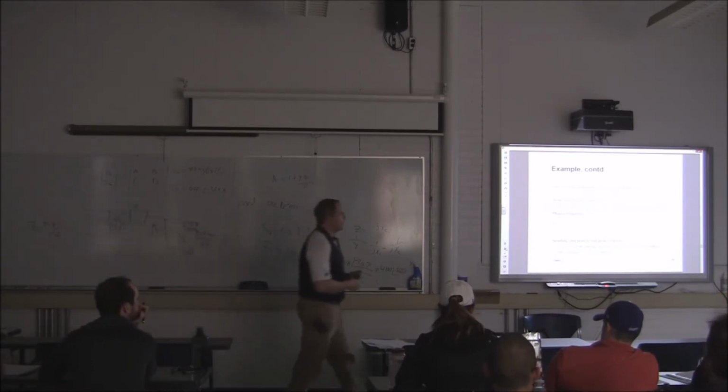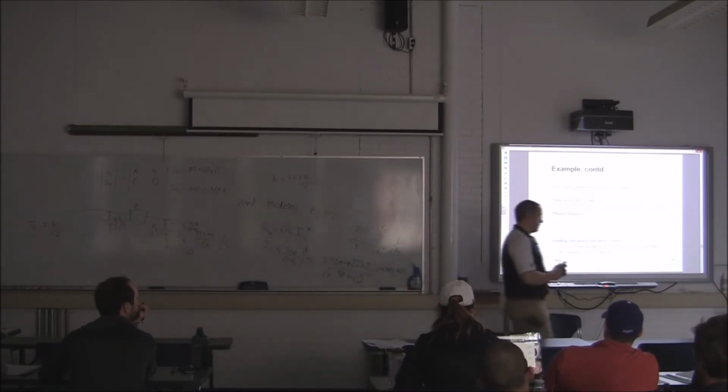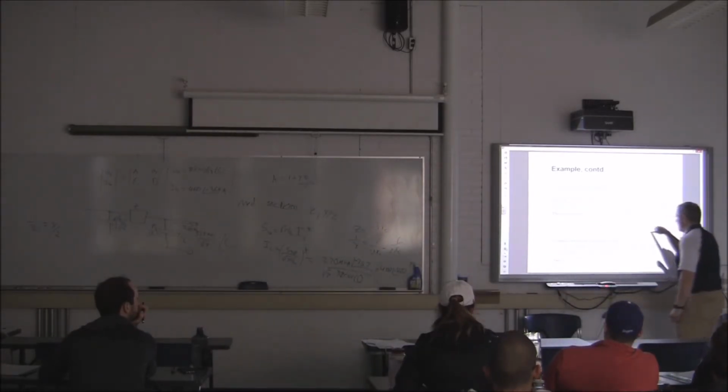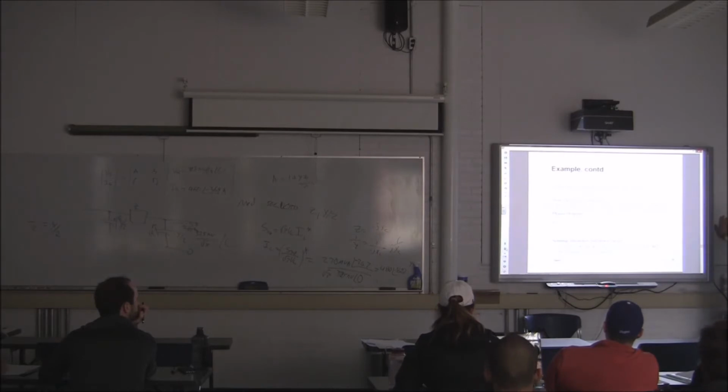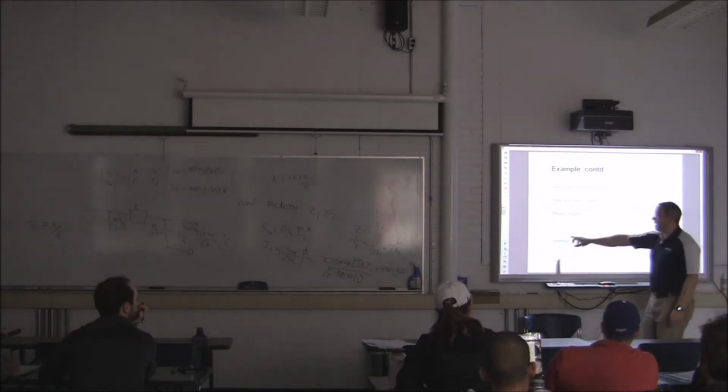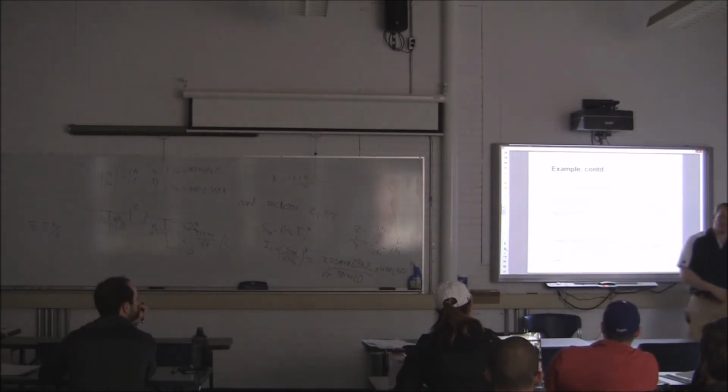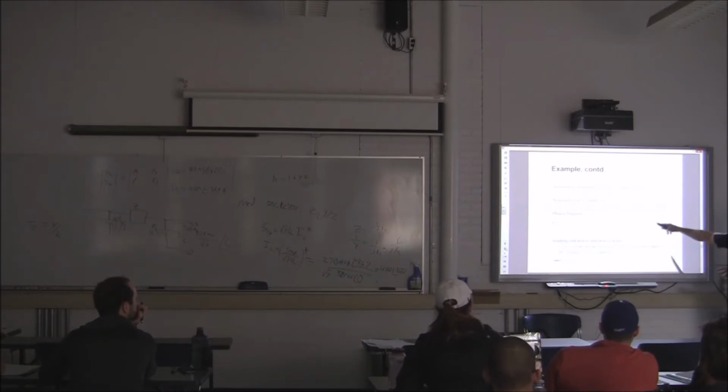And then we can draw our phasor diagram. You'll notice that VR is what? Well, VR is the reference, so it's at 0. IR has a lagging power factor here. That matches. VS has a greater magnitude and a positive angle.